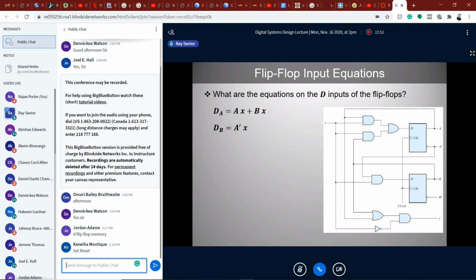And as we can see now, we have generated the inputs to the flip-flop. But since we're using D flip-flops, we know that we want to identify the current states. What are the current states when we talk about D flip-flop? What would you associate with the current states for D flip-flop? Sir, is it the previous state, sir? Pardon me? The previous state. Previous state, and what is that, by the way? Well, in terms of these flip-flops, sir, it would be not A and not B.